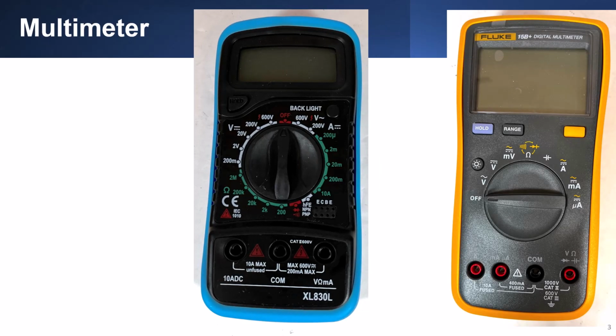Here are two examples of a multimeter. The one on the left has a dial which is divided into three sections. DC voltage measurements are measured with the white settings as indicated by the V with the straight line above the three dots, while the AC voltage measures are measured with the white settings as indicated by the V with the squiggly line. The green values toward the bottom of the dial has the omega or ohm symbol, which is used to measure resistance. The green values on the right are used to measure current as indicated by the A.